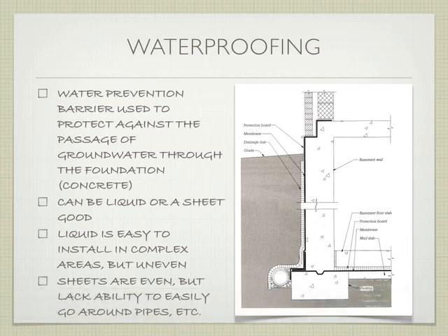So yes, the sump in this case would be permanent. Now, if you have a building where you can naturally collect that water, let's say your building's on a hillside, if you can collect the water at the back, and pipe around the house out to the front where it can naturally drain, then you don't have to have a sump. If you're in an area where you're digging down and you have soil on all sides, then you have to basically pump. You don't really have an option. So it depends on where you are to some extent.